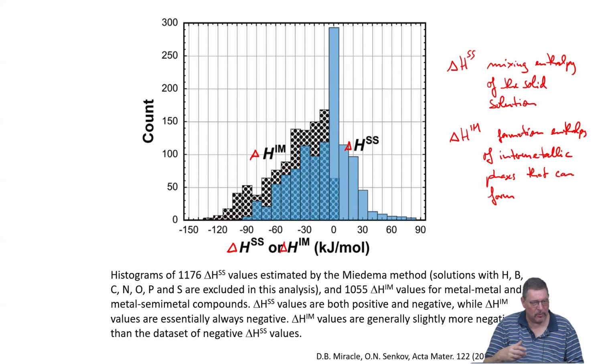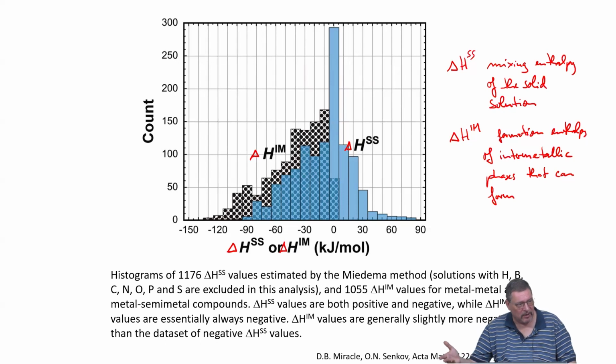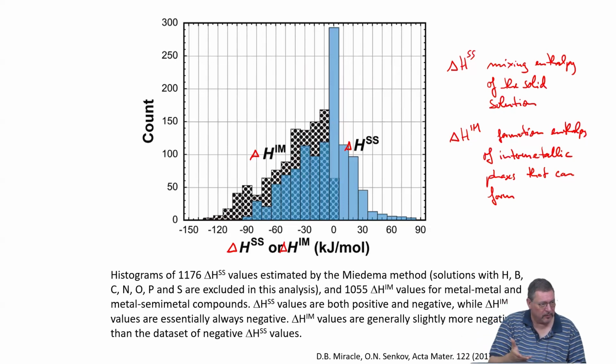So when you compare a calculation with your experiment, you have just made the alloy by maybe some melt cooling process. Now, at which temperature do you compare? Close to the melting temperature, probably you find the solid solution. A little bit closer, maybe still solid solution. Still a little bit closer, well, maybe you still see solid solution, but maybe if you wait 1 hour, 1 day, 1 week, 1 year, you could see it's a two-phase alloy already. But this timeline, how long do you need to anneal?